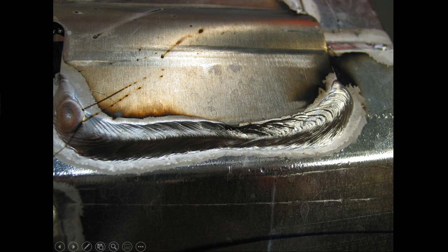And usually it has something to do with, so often, especially if it's consistent, it's the angles of the torch. So if you see an area like this, and this is your skills as a reprocess person, if you see something like this happening consistently, you need to tell the robot techs so they understand every time the robot gets in this position, it's binding the wire.